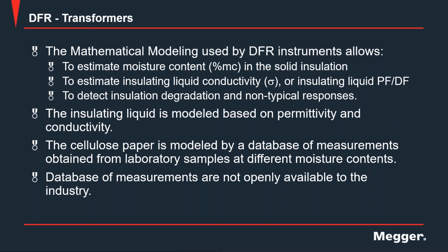The mathematics and the modeling behind the instrument are designed to use different values for the modeling purpose. The most important thing for DFR and the mathematical modeling is to estimate the moisture content in the solid insulation, the liquid conductivity of the insulation liquid, and of course, detect any kind of degradation and non-typical responses.